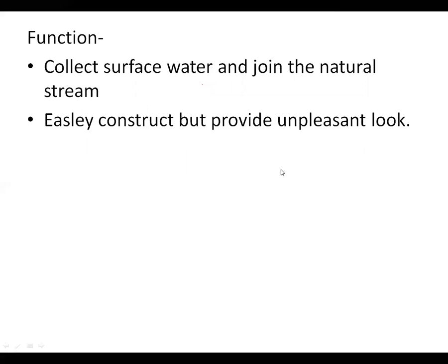The function of a gutter, as usual, is to collect the surface water and drain it to the nearby natural stream. Another thing, we cannot say it is a function, it is a property: it is easy to construct and cheap. Whenever you have to provide an embankment for the pavement surface, you can dig the material from those trenches and put it there, so naturally we are forming the side gutter.